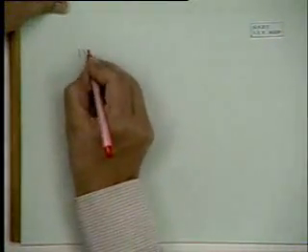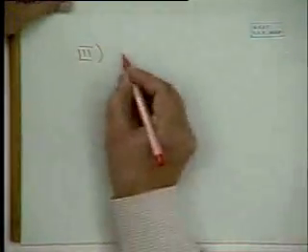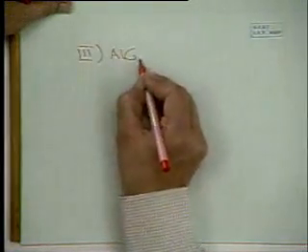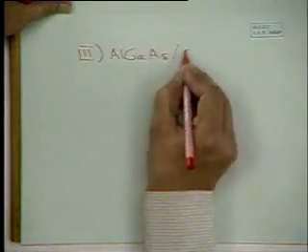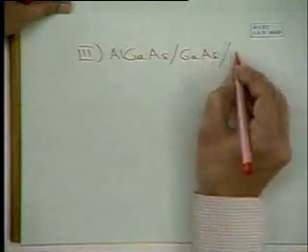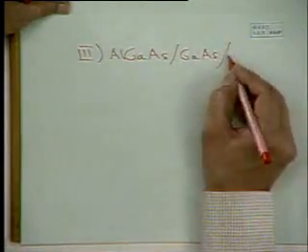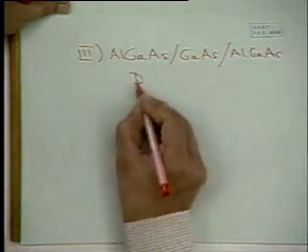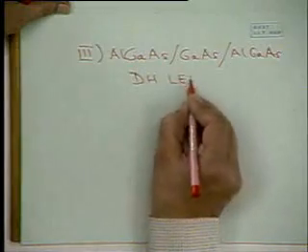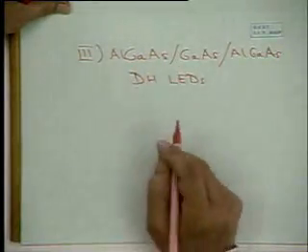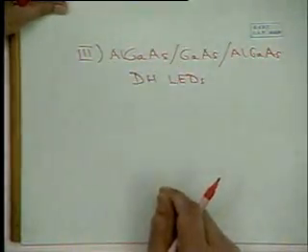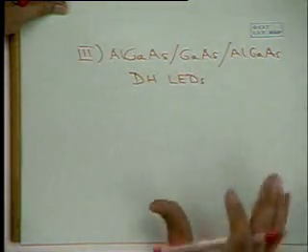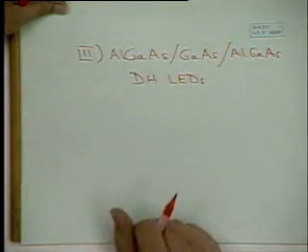What is the third type of red LED that one can talk about? That is based on GaAlAs. These are quite commonplace, and you can get rather higher efficiencies. Why? Because these are double heterojunction LEDs. I drew a diagram of these double heterojunction LEDs, and you will get light confinement, carrier confinement, and you'll get rather higher efficiencies.